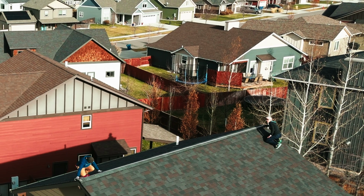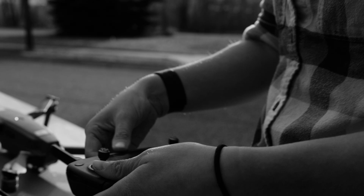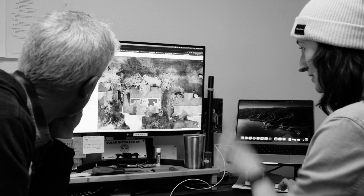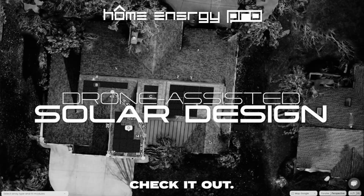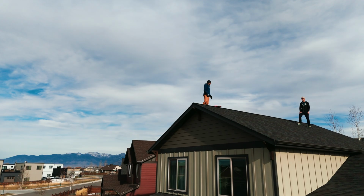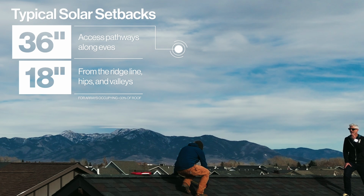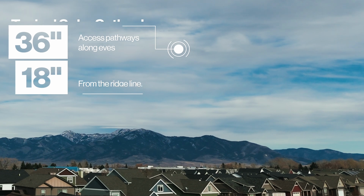Now, a lot of the times, solar companies will do this with drone technology, which we do as well. Drone technology's come a long way in getting exact measurements of a roof. And there are fire code setback distances that we have to keep in mind. If an array takes up 30% of a roof, you must be 18 inches from the ridge cap, 36 inches from any eave, and 18 inches from any hip valley portion of the roof where there's an obstruction.